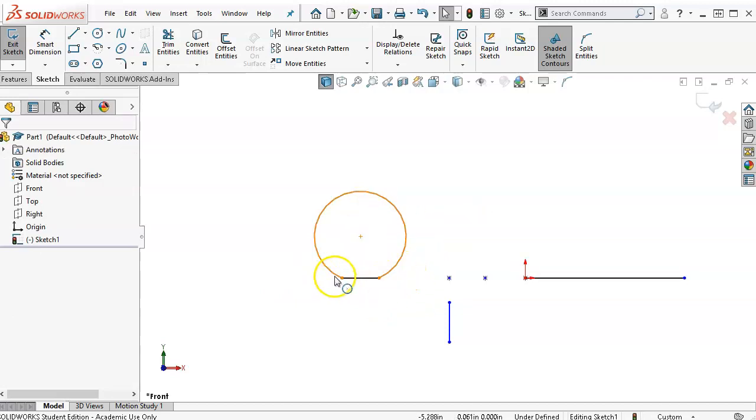Okay, so if I try to make it tangent again, the error was this line is shrinking to 0. A line can't have a length of 0. It could be very, very small, 0, 0, 0, 0, 1, but it still has to have some dimension related to it. So if I were to make it very small and apply a dimension to it, I would see a dimension of 0, but I would have to go out however many decimal places to be able to pick it up.